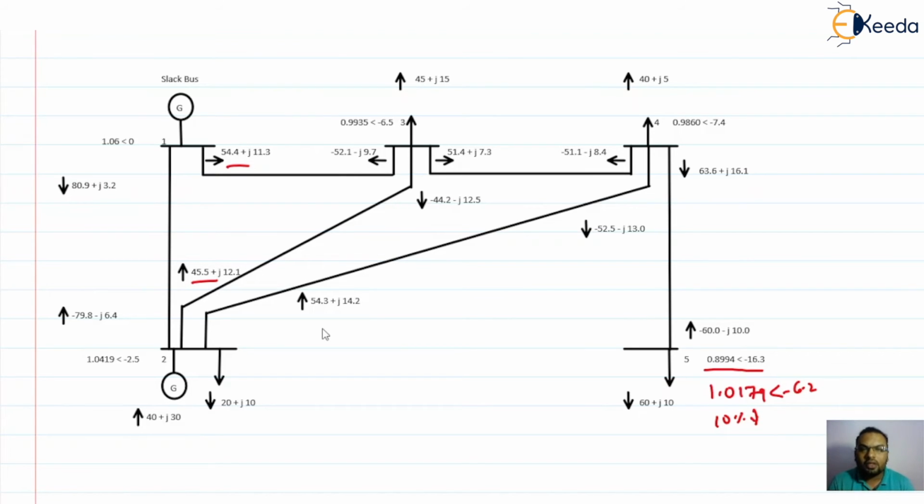Sometimes we can decide the pre-contingency things, like we can do the rescheduling. Let us say I come to know that the line between 2 and 5 is now going to break. The reasons may be a number of things. If I want to take a pre-contingency precaution, I can shift the load of the line between 2 and 5 to other lines, in such a way that the voltages and line flows do not violate their limits. That way we can do. And if it opens, we analyze the things and decide the action plan.